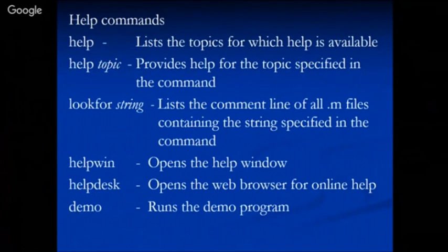Okay, the help commands. help, if you write it, will list all the topics there. Then help topic is there. lookfor string is also there. helpwin opens the help window. Then helpdesk opens the web browser for online help, and demo is there to run the demo program.